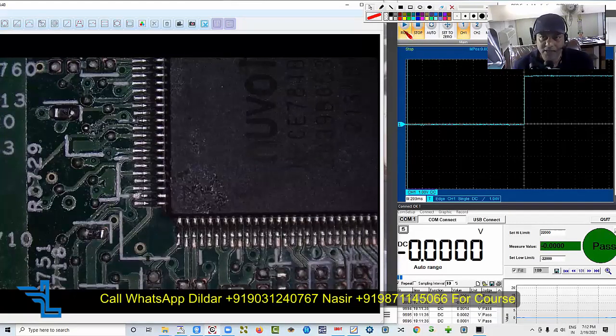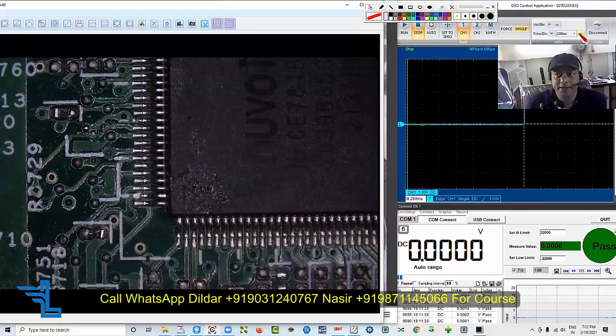Is that right? Because it must go low at some point, it must have the low edge signal at some point of time. So I have checked every setting, if you reduce the time, if you increase the time, check it. The last limit I have checked is 500 millisecond.